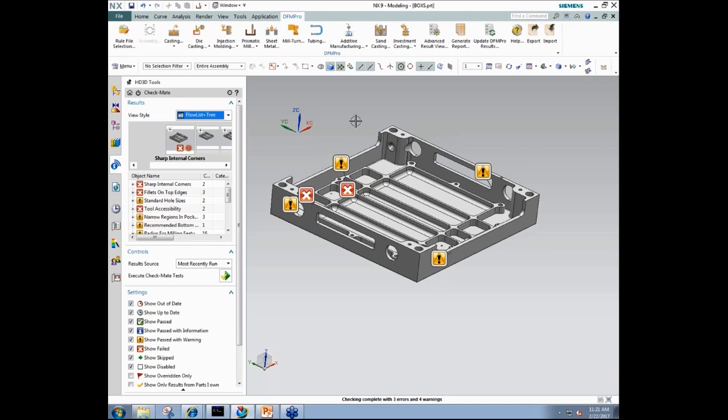Can I machine this pocket very easily? So it will look at that pocket with respect to the milling functionality and the best practices for milling. Likewise, it identifies all these manufacturing features and the corresponding manufacturability validation, and it comes back with this kind of result here.